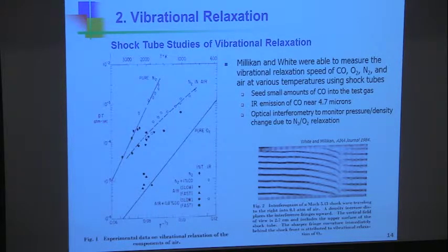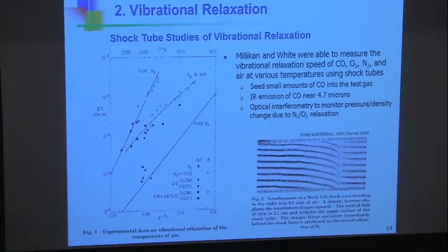So the experiments were done, and so in pure nitrogen, for example, at 2,000 degrees, looks like it'd be about 10 to the minus 3 seconds if you're at 1 atmosphere. So it's about a millisecond at 1 atmosphere at 2,000 degrees. So the question is whether a millisecond is fast or slow for you. If, on the other hand, you do pure oxygen, now it's quite a bit faster. At 2,000 degrees, that's probably about, I don't know, 8 microseconds or something like that. And if you have some sort of mixtures of nitrogen and air, it's going to be in between.